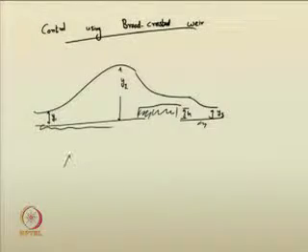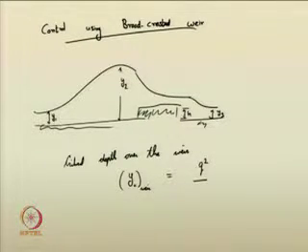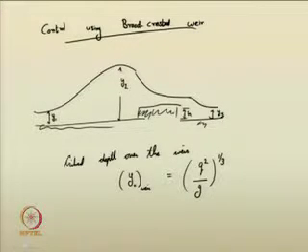So, you know that the critical depth over the weir, this can be given as yc over the weir. This is equal to the discharge per unit width, q squared by g, whole to the power of 1 by 3. This I hope you can follow, as we are all taking the rectangular weir, that is the reason. So, q is discharge per unit width. So, applying the conservation of specific energy theorem in these particular situations, say in these following sections.